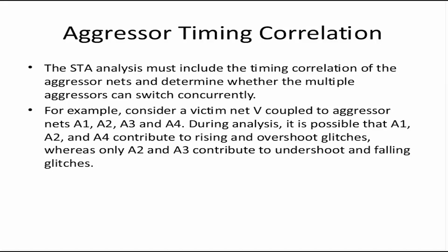So what does PrimeTime do? Please note that PrimeTime is a timing tool. For example, if you talk about a register to register timing path, it knows when the nets between these two registers are switching and what the baseline is. The baseline here is clock switching.